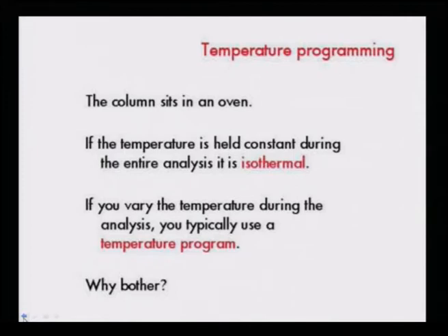So, this is up to the analyst to understand whether there is a need to have a ramp or temperature programming, or whether one can carry out the analysis keeping a constant temperature, say at 180 degrees. But that is a little risky if you have both low boiling and high boiling components. One cannot jump into those very easily.